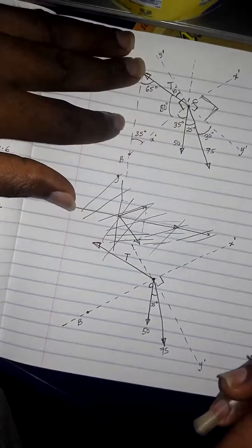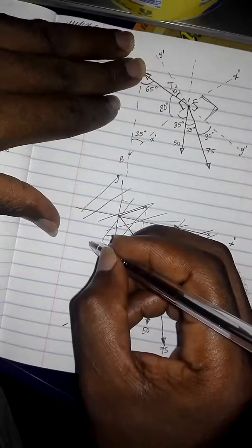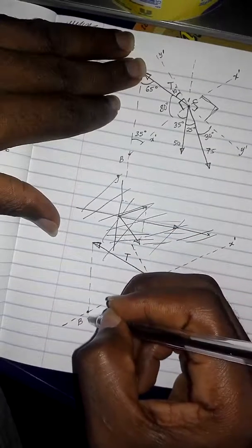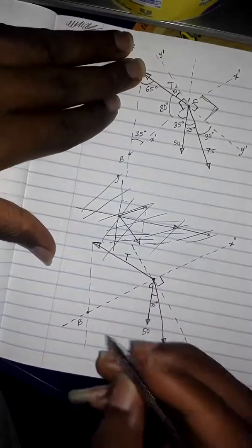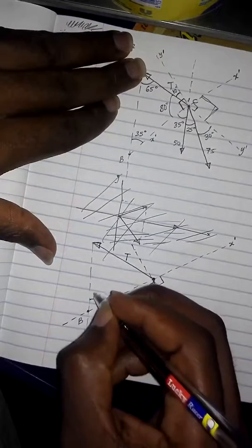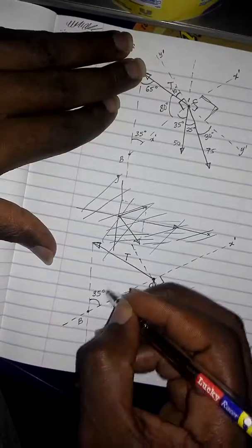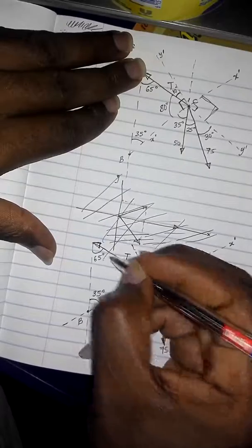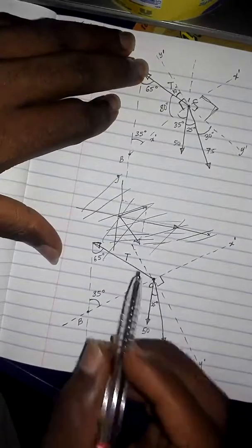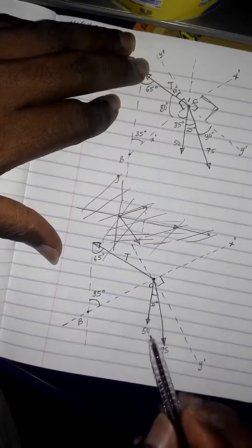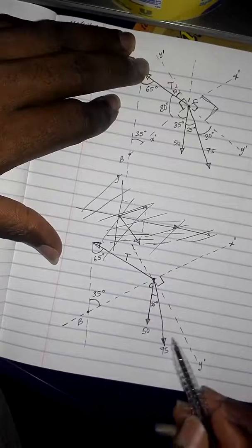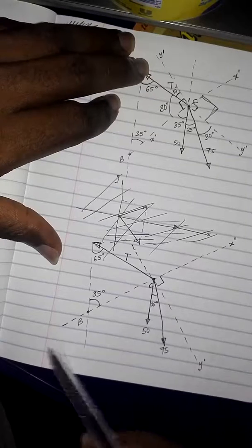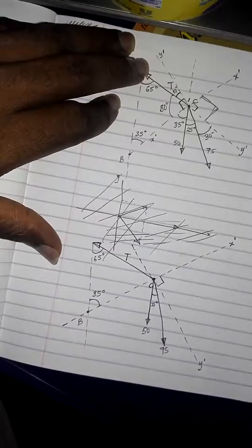Alright. So from the diagram, if you extend this downwards, you have something like this. This is the vertical line, and the diagram says that this angle is 35 degrees and this angle is 65 degrees. Alright. So these are the three forces: this force T, this force 50 pounds, and this force 75 pounds. And I have been told that their resultant is along this direction, and this is the perpendicular to the direction.